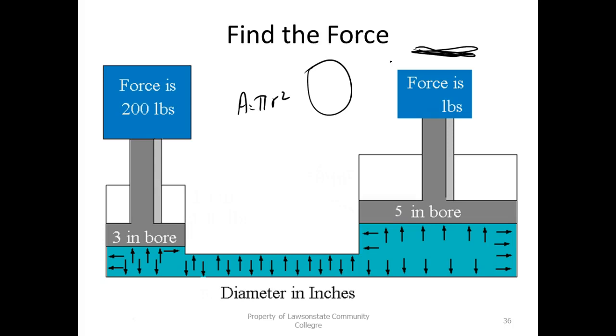It would be very inefficient. First thing, it'd be hard. It's hard to seal around a corner. So it's real easy to seal around a circle. But when you come to that corner, it would be hard to make a seal that made a 90-degree turn. So you always have leaks at the corner.